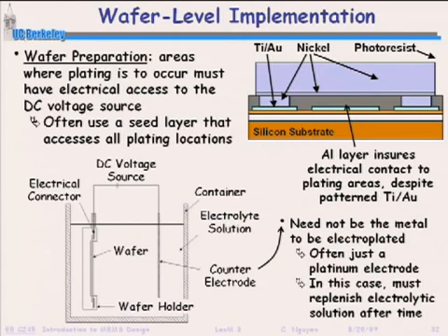You have a holder here that ensures you can get electrical currents around all edges of the wafer, so it's in contact along all edges there. That gives you very uniform current distribution around this wafer, which gives you very uniform electroplating. And the rest of this is just like the high school experiment. It is the high school experiment, except you're being more careful about the solutions you use, the concentrations, and the currents that you're driving with. And that's it for film deposition and oxidation.